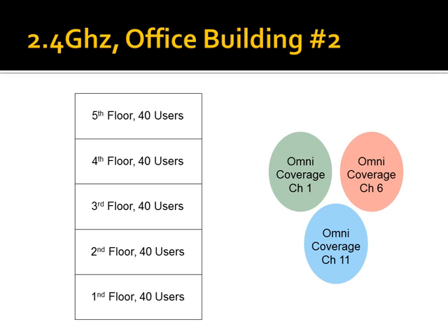Now, we talked about directional antennas. The actual term I'm going to start using is sector antenna, because basically a sector antenna is a directional antenna that has a particular radiation pattern in vertical and horizontal. This is the horizontal beam width. So we're talking about 90 degrees. Vertically, sector antennas have a fairly narrow pattern, maybe 10 to 15 degrees. Okay?